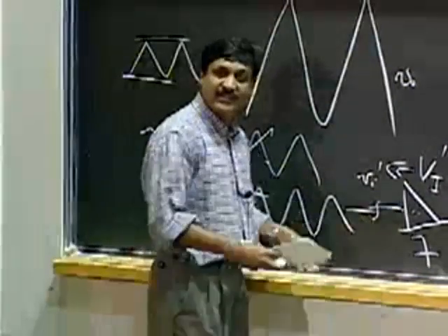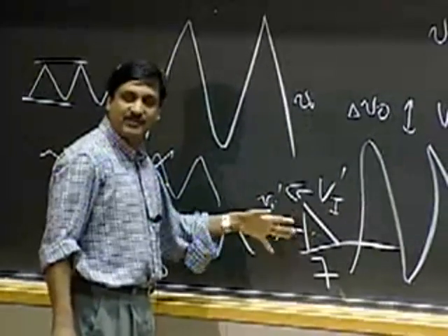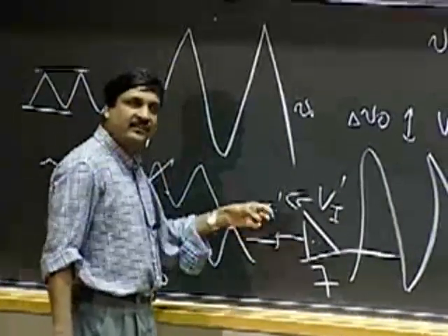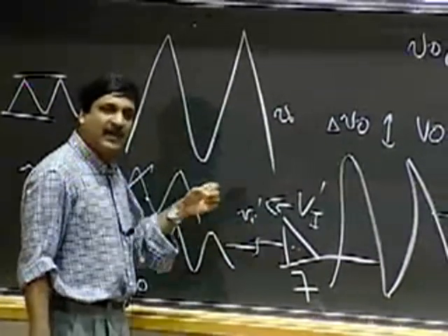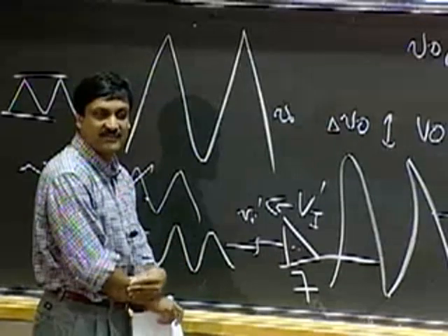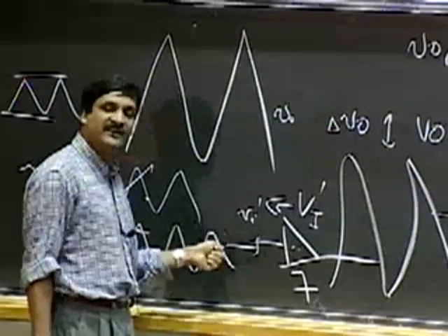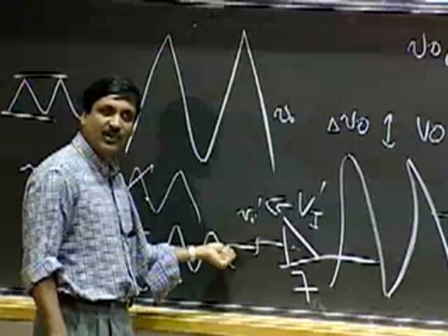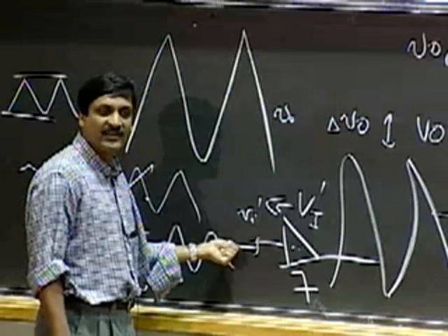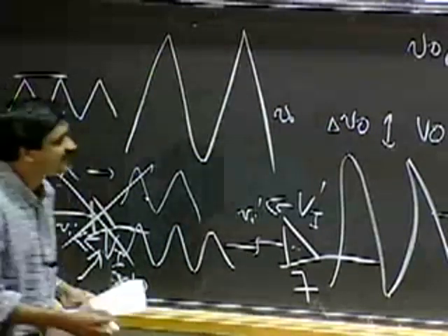It turns out that when you have large voltages and practical devices, the more current you pump through devices, they tend to produce noise of various kinds. So very powerful amplifiers are not very good at dealing with really tiny signals because they have some inherent noise capabilities. And so I guess that is sensitivity. It's sensitive to noise. So okay, another question?